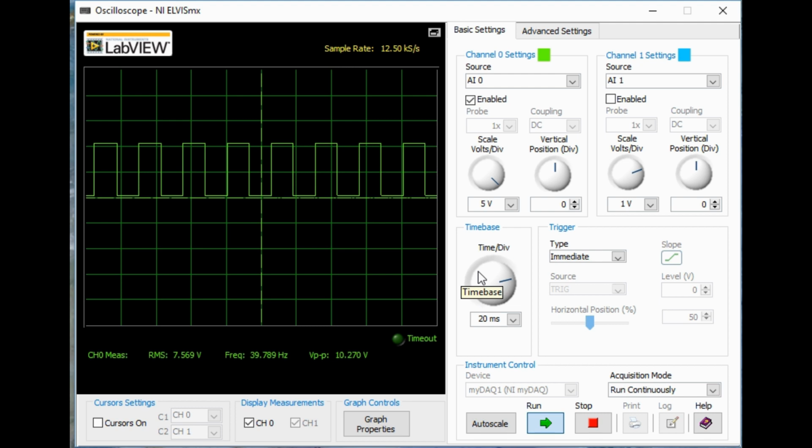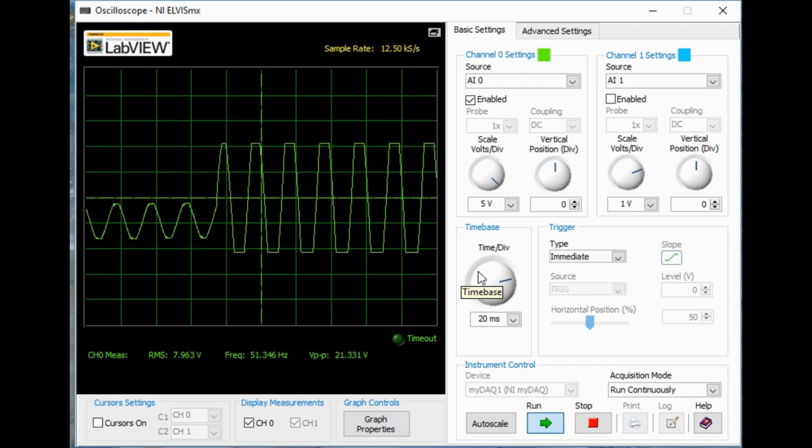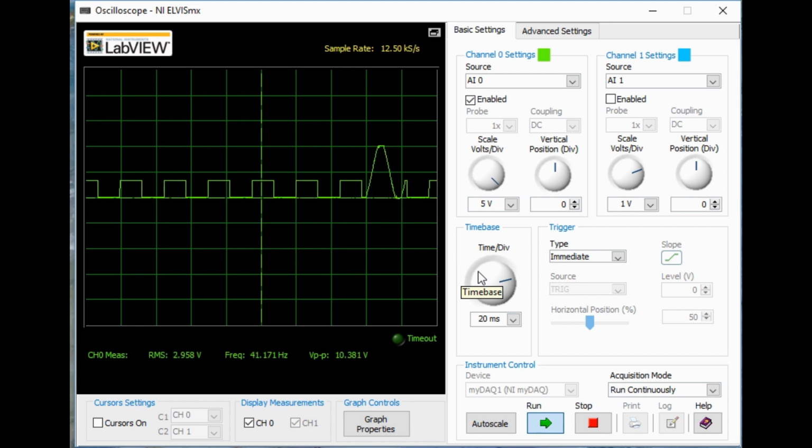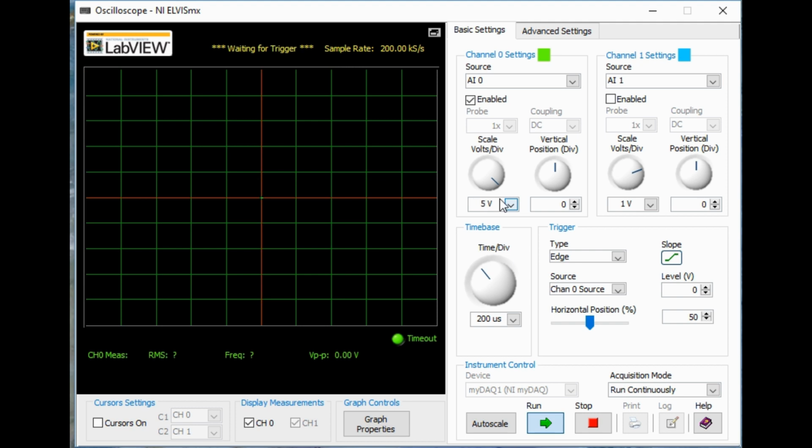And I can take this out and we can plug it into, let's have a look, the low side signal. So this is what's coming from the myDAQ to the IR2110. See, it's a lot lower. Unfortunately, we don't have the resolution with this to see any turn on times. I can trigger it on an edge trigger. Put that up maybe. So there we go. It's triggering very badly, unfortunately. Let's do the equivalent of a single shot trigger.